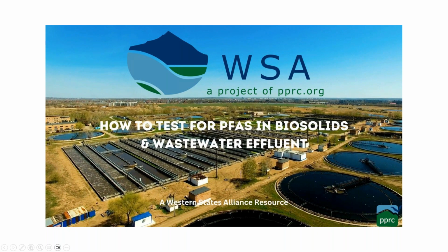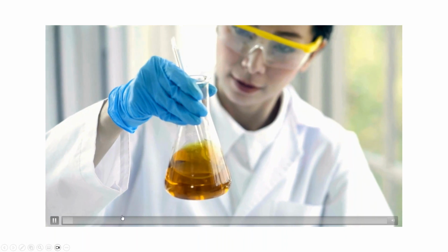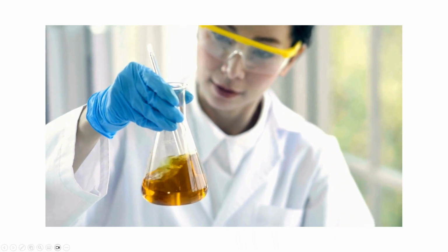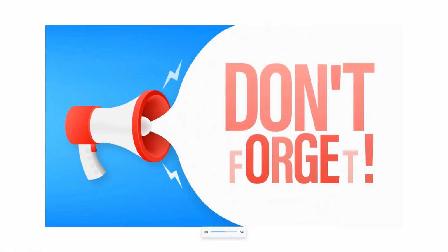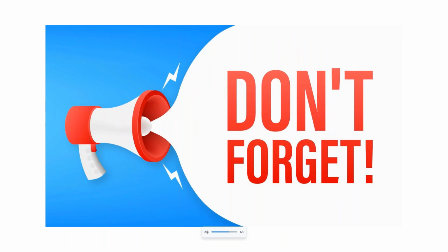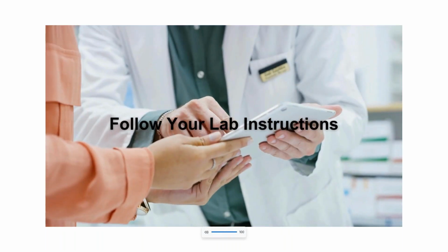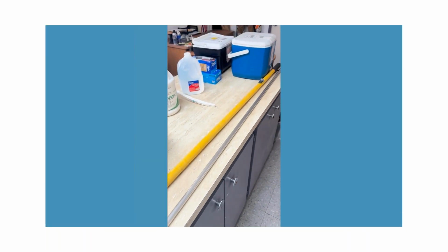Yeah, it's very faint. This video shows the equipment and methods recommended in general for PFAS sampling for wastewater. It's important to not contaminate any of the equipment with personal care products or items that may contain PFAS. Follow your contract lab's instructions. We're getting ready to sample PFAS for both biosolids and wastewater.